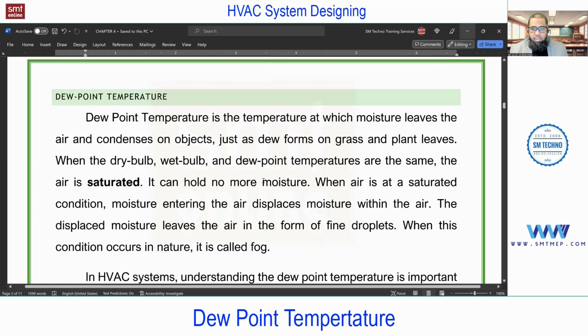Back to the topic. So I think you got the idea about the dew point temperature. Does it depend upon the load on the evaporator? Meaning 1.2 liters per hour. That is a standard. You see, 1.2 is just a standard, like a thumb rule, like 1 TR equal to 400 CFM, right? Similar to that. But this may vary because extraction of moisture depends on the condition of the room also, right? If the room air moisture is less, so how will it extract?